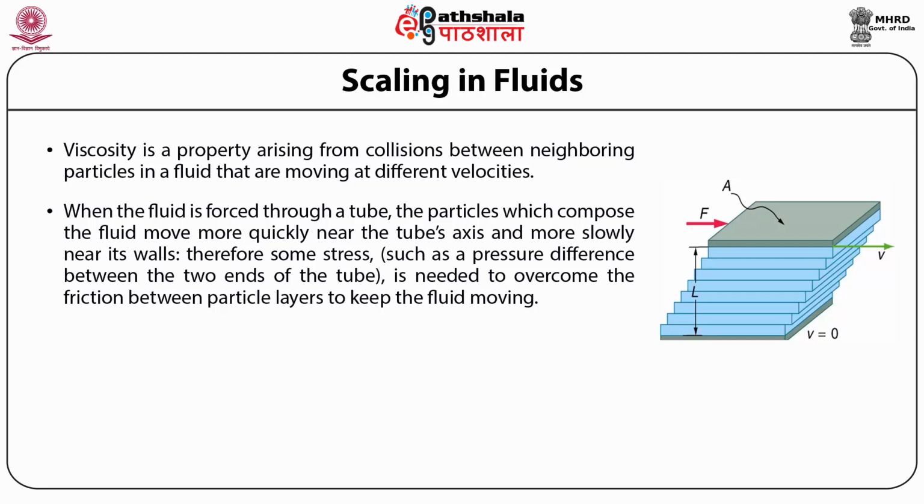So this results in some stress, which is the pressure difference between the two ends of the tube, needed to overcome the friction between the particle layers to keep the fluid moving.